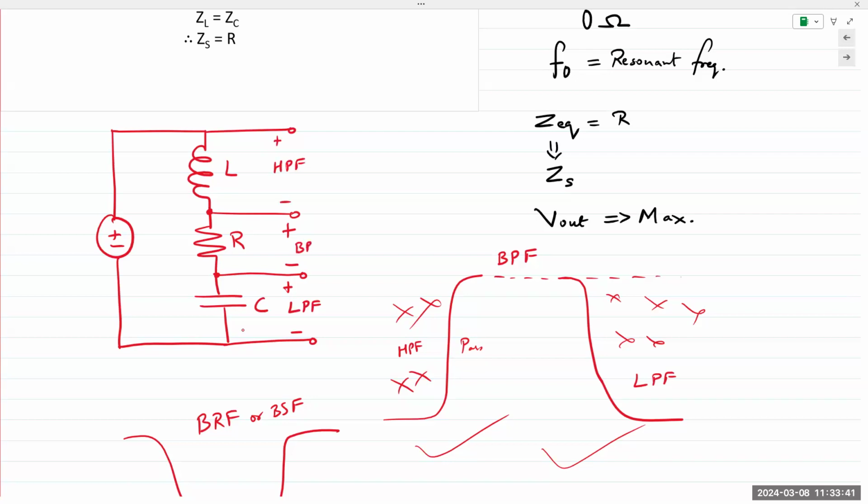And this is, going back to the beginning of chapter 6, a high quality crossover network, where a speaker can take an incoming cable and split it into 3 different outputs. It goes into 3 different speakers. And that's why I said a high quality speaker would have a high quality crossover network, with huge inductors, capacitors, and resistors. Cheaper ones would simply be built out of capacitors.